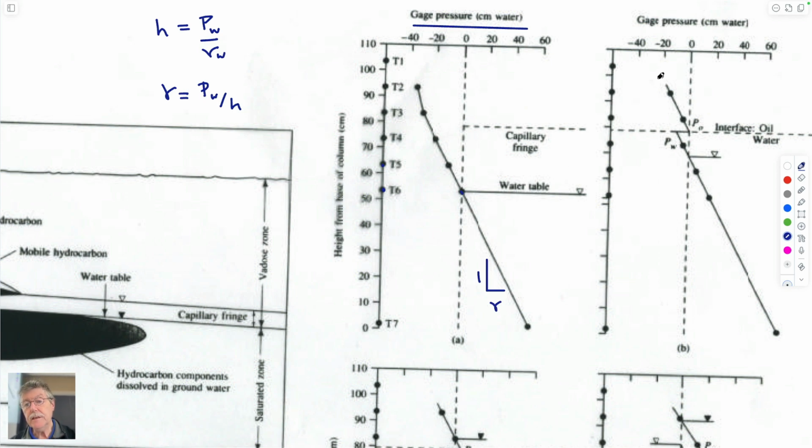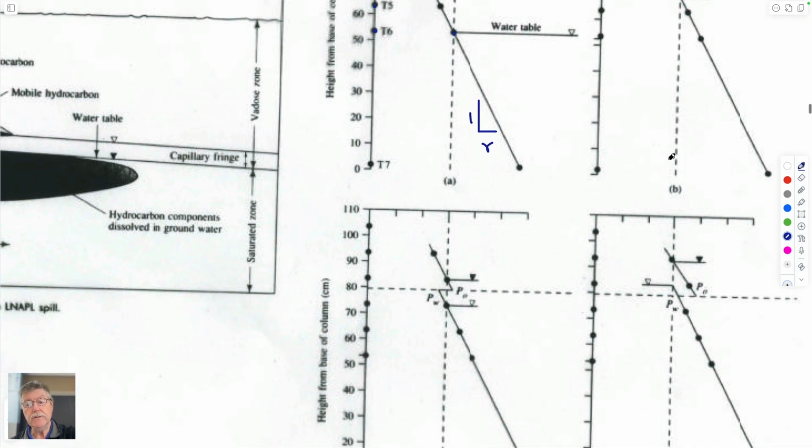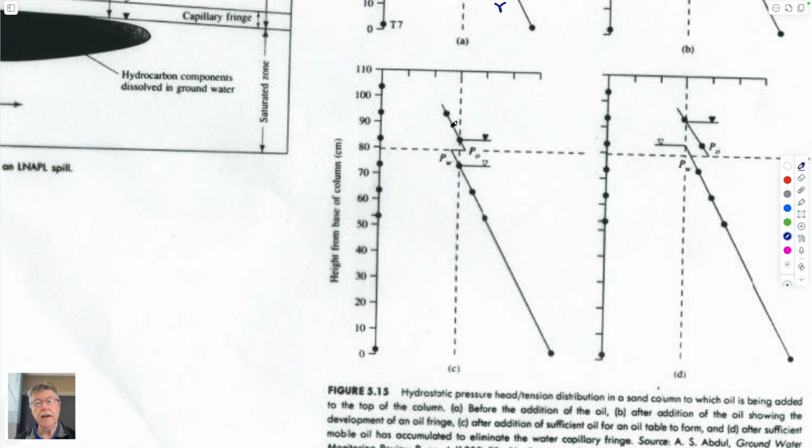So you dump the gasoline in. It's still lighter than the water. So now you get this little nose of gasoline, which has atmospheric pressure at the base, and it's come down through the system to rest on top of this capillary fringe. The water distribution in the liquid column, the water column, is still the same as it was, unit weight, but now it's putting pressure on the top here. You allow it to continue, and this nose slowly just settles down.